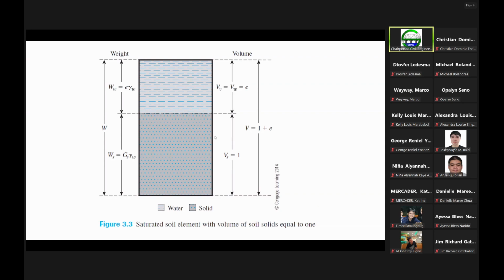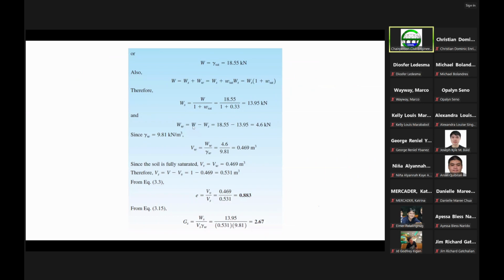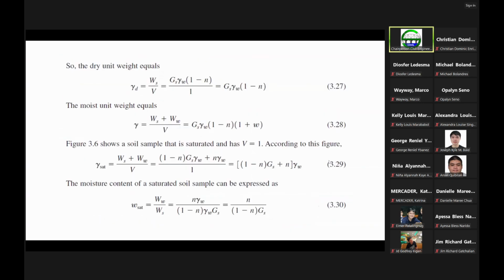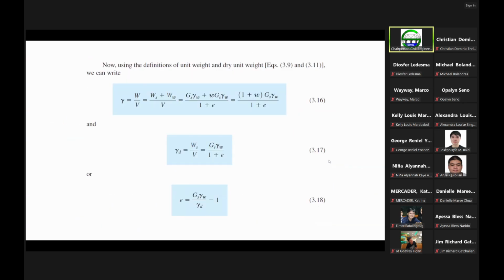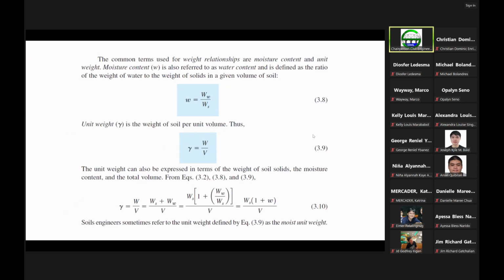So if we go back, the weight of solids plus the weight of water, but we know by definition that the water content is defined as the weight of water over the weight of the solids. Let me go back to that definition again. Here.